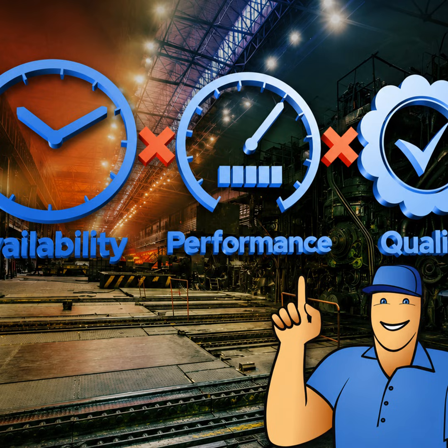Your performance calculation looks like this. Performance equals ideal cycle time times total count divided by runtime. In this example, that means 2 times 204 divided by 465. That equals 87.7%. So your machine ran about 12% slower than its design speed, possibly due to one or more reasons. Finding those reasons may require a root cause analysis.